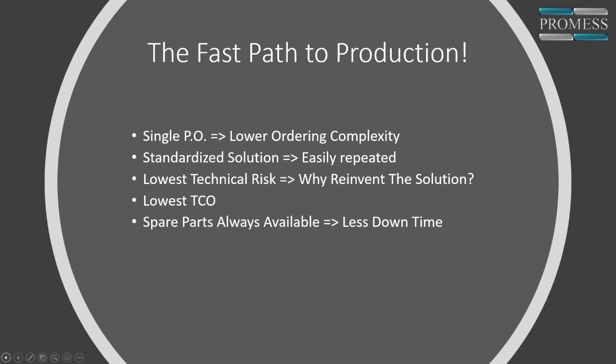Correct. How accurate are your torque readings? On our standard torque products, our accuracies are better than 1% of full range. So basically, on a 20 Newton meter unit, you're going to be accurate to better than 1% of its torque reading.